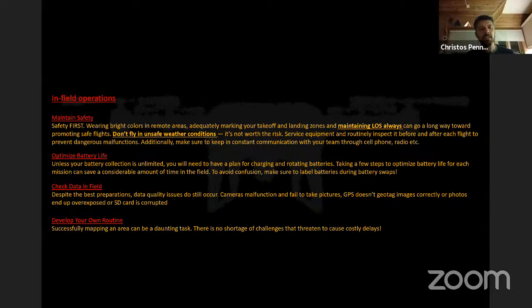We should always check the data that we are collecting in the field before we go back to the office, because if we miss something, if we spot something strange, if we find a mistake that we have probably made, it is always better to fix that mistake in the field instead of going one more time back and working there. And of course, you should develop your own routine. So one who is planning to deploy drone missions should develop, in time, his own routine, where he will take all these things that I mentioned into consideration.